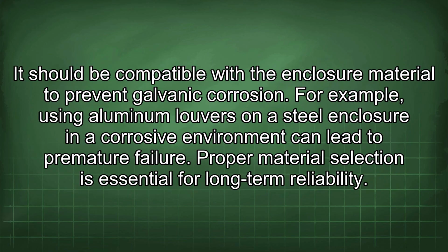Also, consider the material used for the ventilation slots or louvers. It should be compatible with the enclosure material to prevent galvanic corrosion. For example, using aluminum louvers on a steel enclosure in a corrosive environment can lead to premature failure. Proper material selection is essential for long-term reliability.